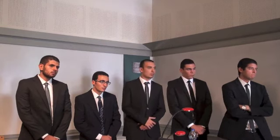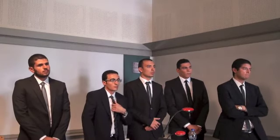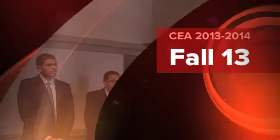Any other question? One comment regarding the similitude. When you choose to scale in half, and you do the assembly, you may find that you need to scale down the reinforcement to some non-commercial size, and we may need to use wires instead of the commercial reinforcement. So that could be one of the challenges. So please consider that in your scaling.